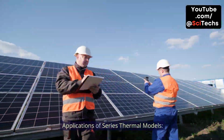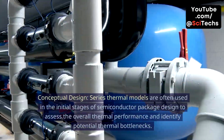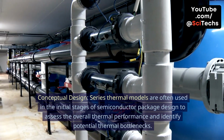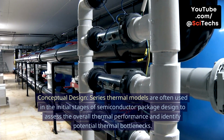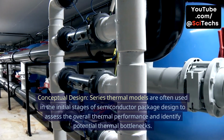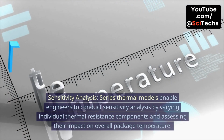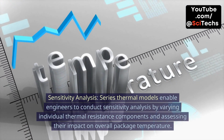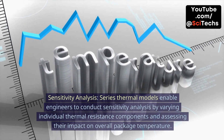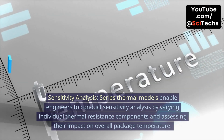Applications of series thermal models. Conceptual design. Series thermal models are often used in the initial stages of semiconductor package design to assess the overall thermal performance and identify potential thermal bottlenecks. Sensitivity analysis. Series thermal models enable engineers to conduct sensitivity analysis by varying individual thermal resistance components and assessing their impact on overall package temperature.